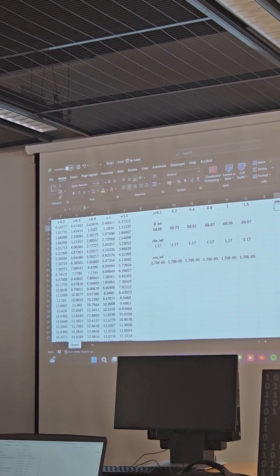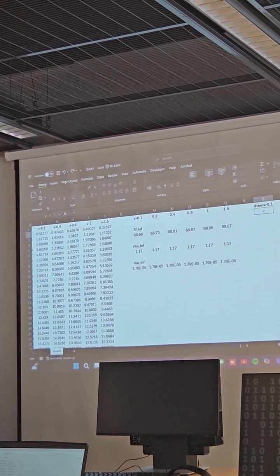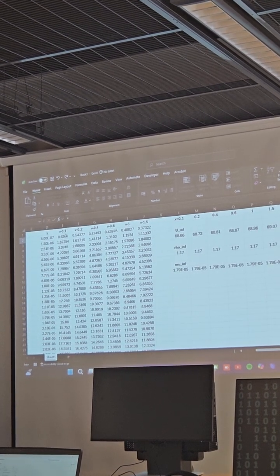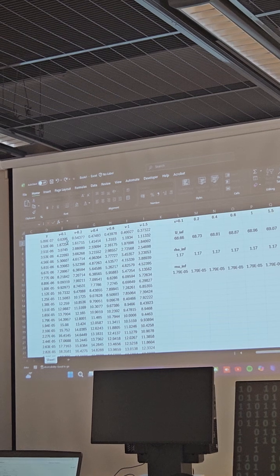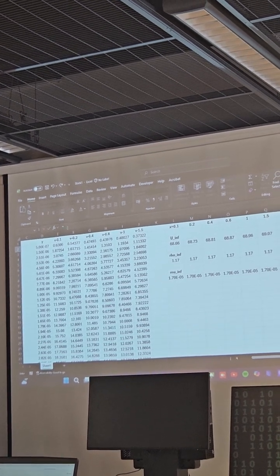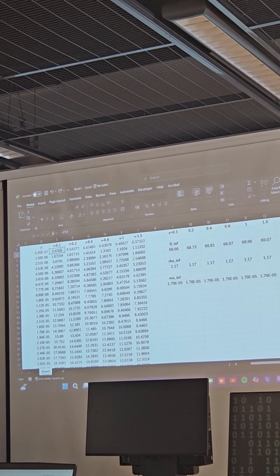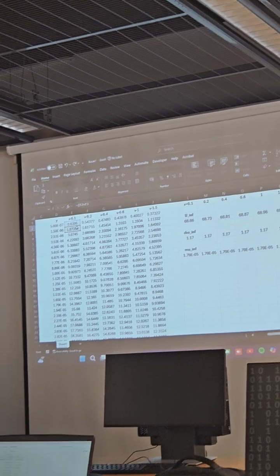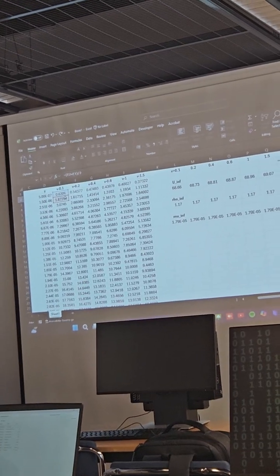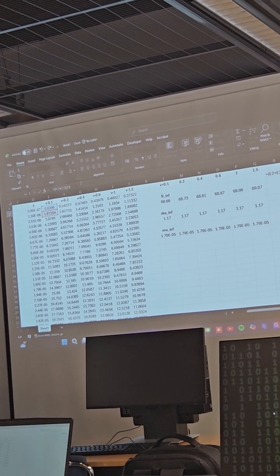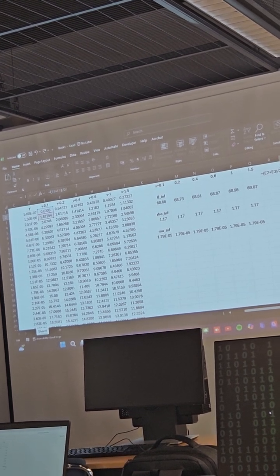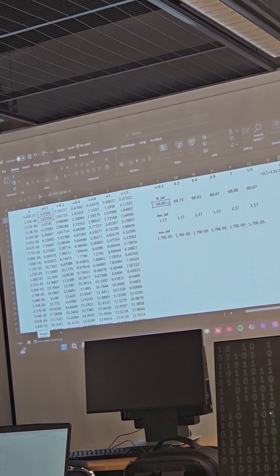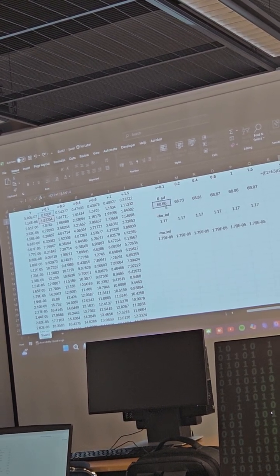So we need to implement that formula. So that's going to be uy. So which uy? You can use either one of the two extremities point or an average value. So I'll go for an average. So I select this plus this, so the 2 points of my interest over 2. This is uy over u infinite. So the u infinite for x equal to 0.1. This is 68.66 for me.